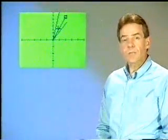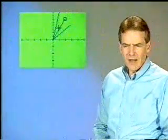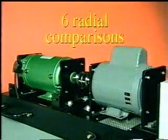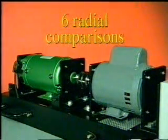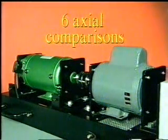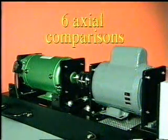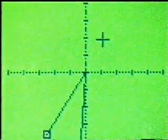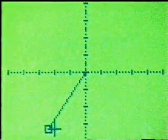Static phase measurements provide another tool for diagnosing many machinery conditions. Remember that because phase measurements provide amount and direction, they can be displayed as vectors to show the machine's motion. Use the 6 phase comparisons in the radial direction and the 6 phase comparisons in the axial direction. Be sure to take into consideration the orientation of the sensor. The directional phase comparisons, as well as some erratic phase conditions, point to specific machinery faults.